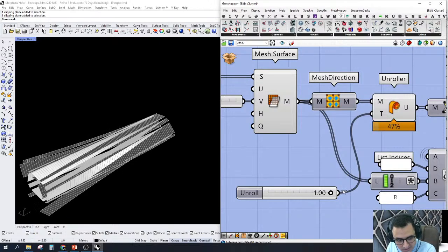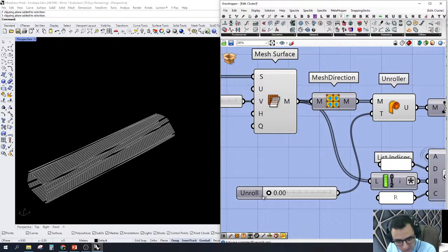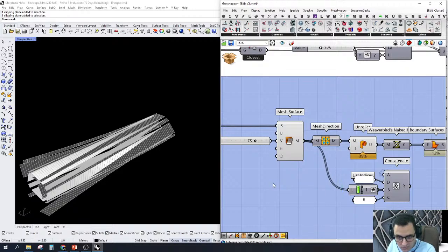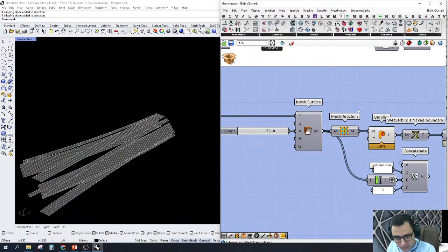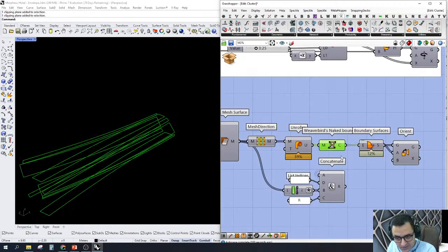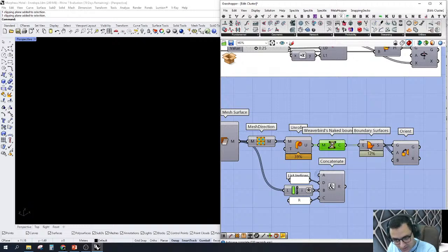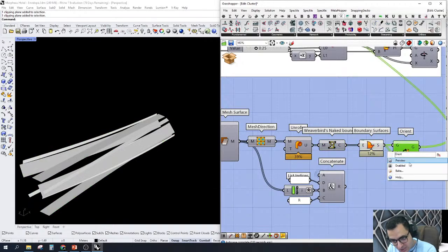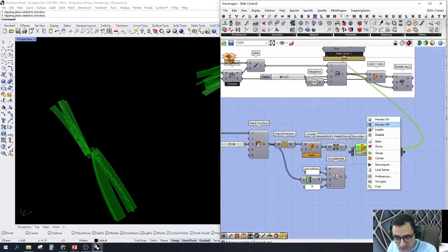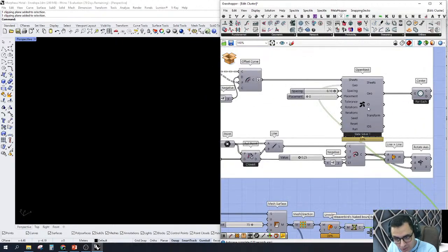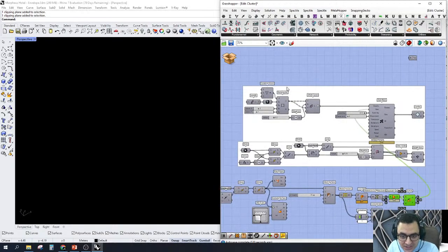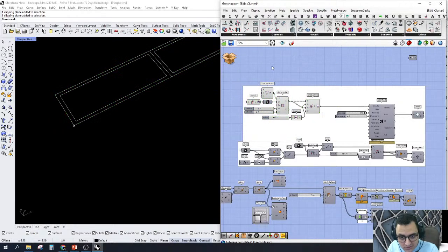You can see that 0 is unrolled and 1 is totally rolled. And again, these are the edges, and after unrolling them they can be surfaces, and simply orient them to be like this. And after orienting them, we can start the Open Nest and insert them inside the Open Nest. But before we do that, we need to create the sheets. So preview on, these are the sheets.